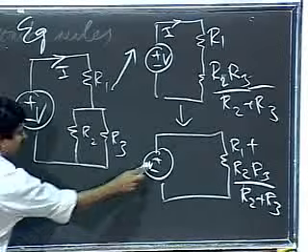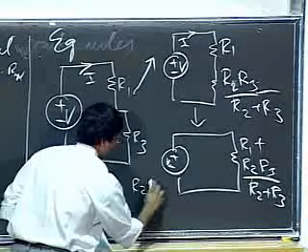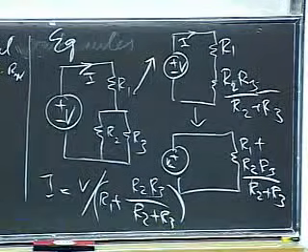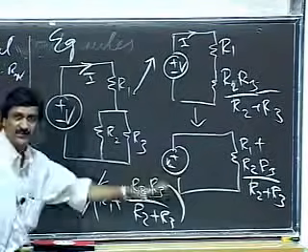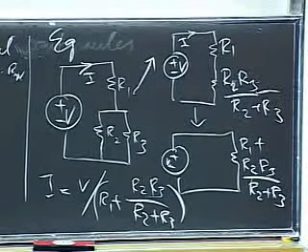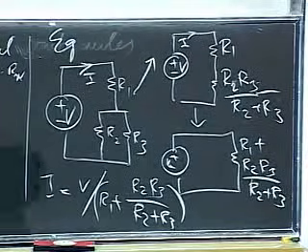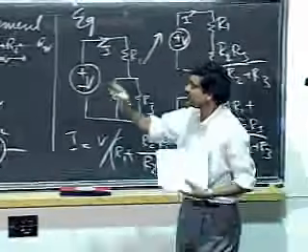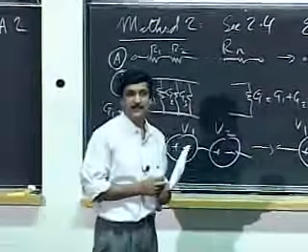I is simply the voltage V divided by R1 plus the rest. Okay? So in situations like this, where I'm looking for a single current, I can very quickly get to the answer by applying some of these element combination rules, and I can get rid of having to go through a set of formal steps. So in general, whenever you encounter a circuit, by and large, attempt to use intuitive methods to try to solve it, and go to a formal method only if some intuitive method fails.